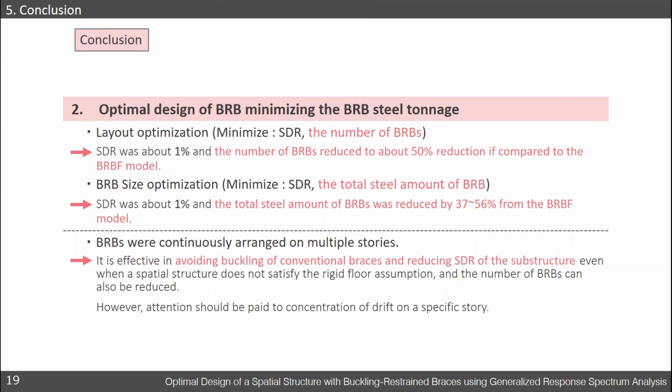While the story-based concentrated BRB configuration working as energy dissipation stories is sometimes not recommended, because it is equal to a soft story mechanism, the hybrid configuration of the concentrated BRBs along both the stories and the elevations was truly the optimal solution for the enhanced seismic performance of this specific large span music arena.